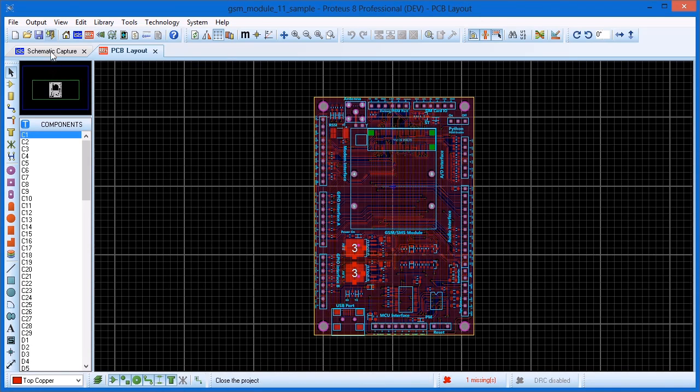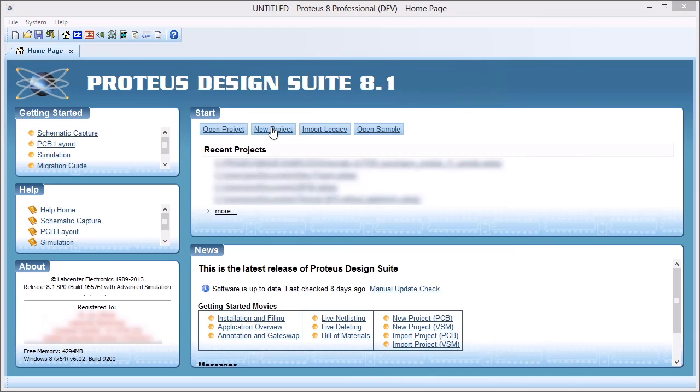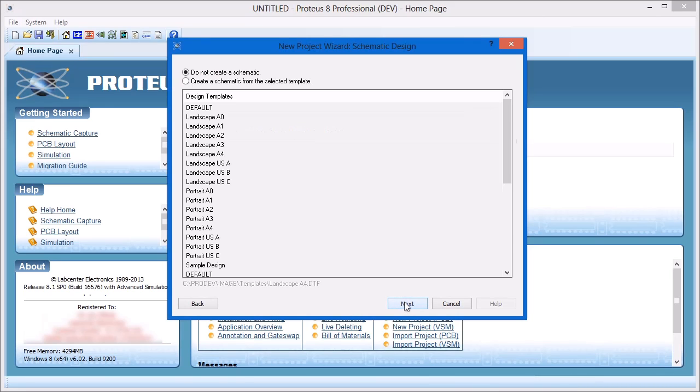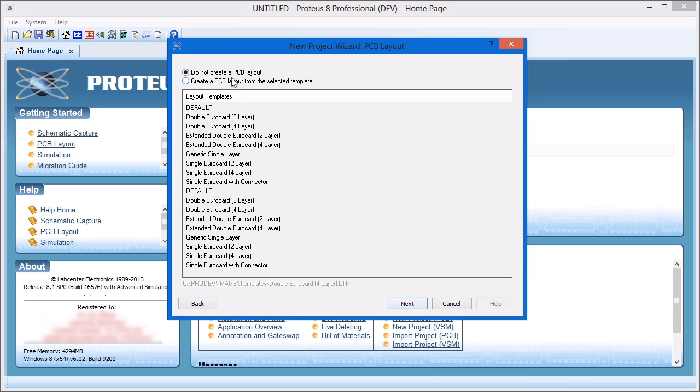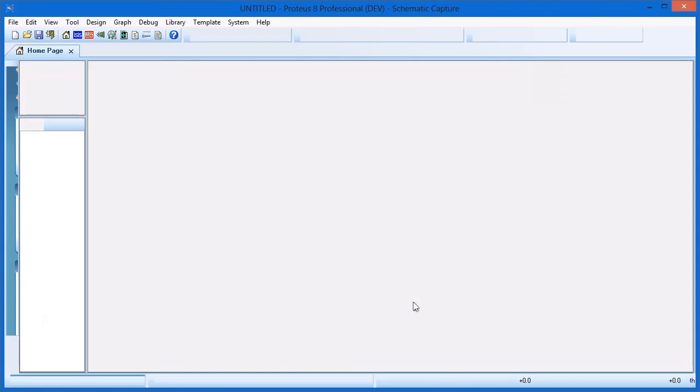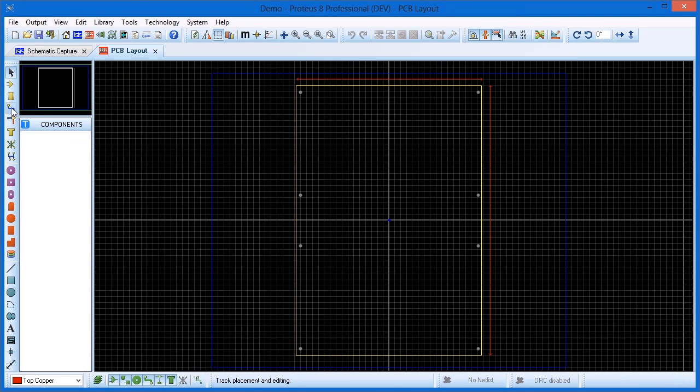Finally, the new Project Wizard allows you to directly adjust the layer stacks defined in the PCB template. You can add or remove inner layers as well as renaming them for the current project. During board layout, this simplifies the selection filter for operations like track placement.